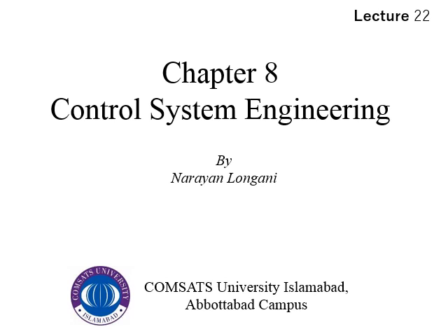Third one, on real axis, the root locus exists to the left of an odd number of finite or infinite open loop system poles or zeros. Fourth one was the root locus will begin at the finite or infinite poles of open loop system and will end on finite or infinite zeros of open loop system.